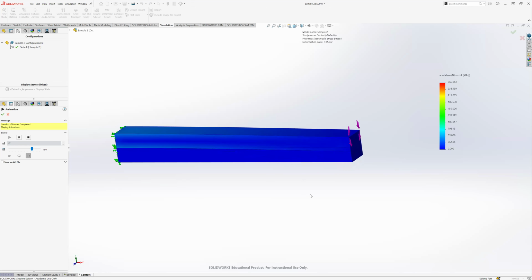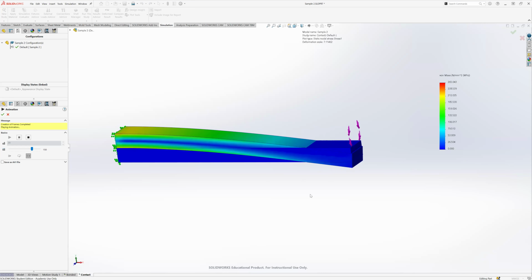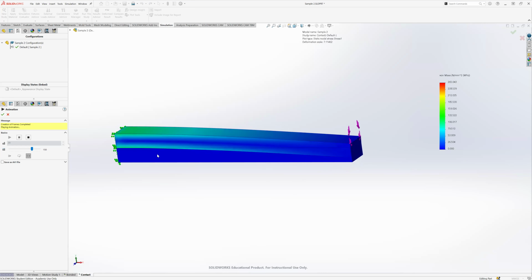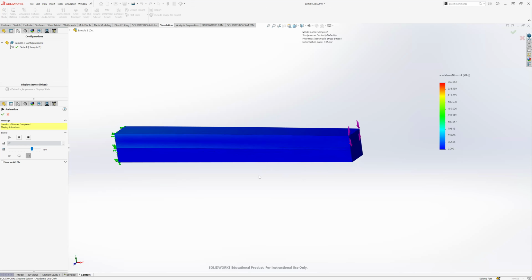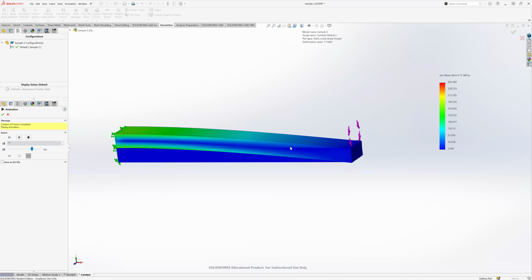That's what they mean by contact, because that's what they used to call it in simulation. Then they changed it, I think, within the last few years. So if you watch any videos on YouTube or any things that are a little bit older, you might hear people talking about non-penetration, and you might look in your SolidWorks and not find a non-penetration. That's a contact condition. Okay, so we have that.